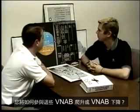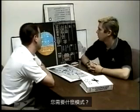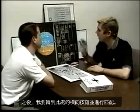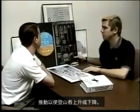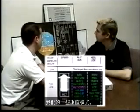How would you engage these VNAV climb or VNAV descent? What modes would you need? Well, first of all, I'd have to have NAV mode engaged. And after that, I'm just going to go to the altitude button right here and push it to get climb or descent.